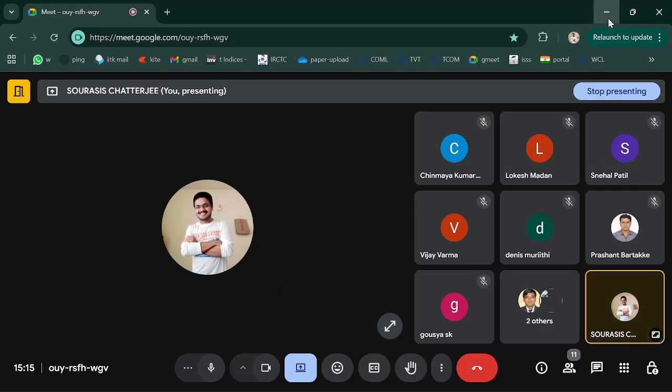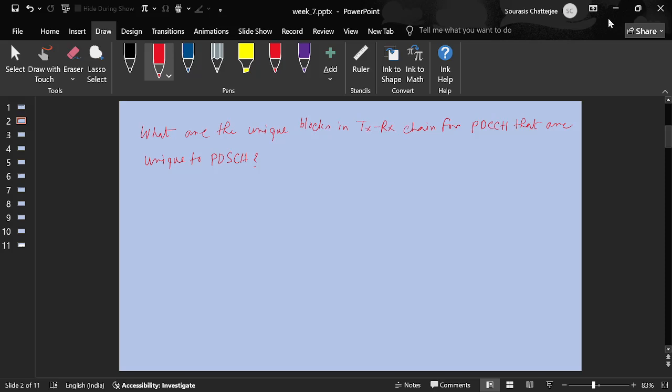Okay, so what I was asking is that when a user is entering a network, it still needs some control information for letting the base station know that it has entered, and then the scheduling will come later. That's okay. But at this point there is no C-RNTI for it, like there is no user specific identity. So how does the transmission happen in that scenario?